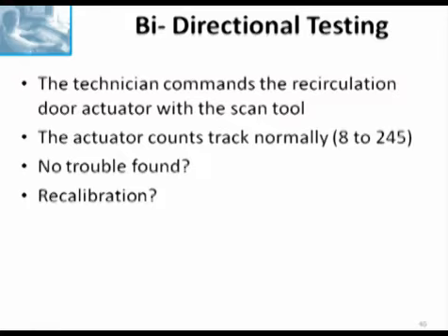It's only about 80 degrees. Now a lot of guys, when they run into one of these, find that if they recalibrate the system at this point, and they drive the truck around, everything feels great, sounds great, and the ticking noise goes away. And that'll work until the next time the temperature gets really hot and cools down again, and whatever those conditions are get recreated, and the door perhaps sticks in a particular position and resets the code. So recalibration of the doors is not the answer to these types of codes.